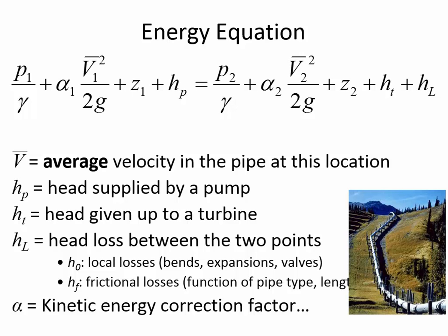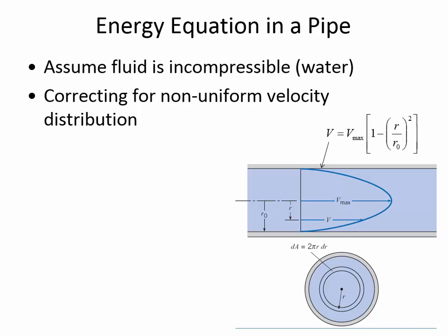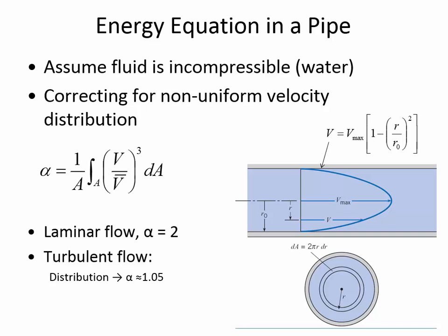But it's very uncommon to have laminar flow. You saw in the lab when we were working with the Osborne-Reynolds apparatus that injecting the dye, we had to really crank the flow rate down extremely low to encounter laminar conditions. And so it's far more common to have turbulent flow. And the kinetic energy correction factor that you should use for turbulent flow is 1.05.